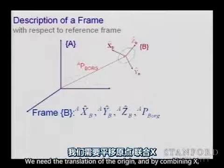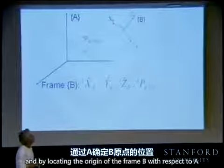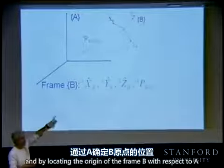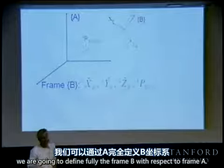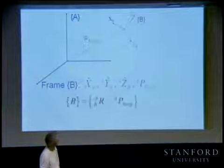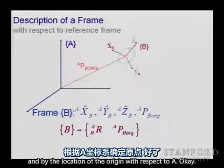We need the translation of the origin, and by combining the description of the rotation, that is those vectors, and by locating the origin of the frame B with respect to A, we are going to define fully the frame B with respect to frame A. So the frame B is essentially defined by this rotation matrix B to A and by the location of the origin with respect to A.